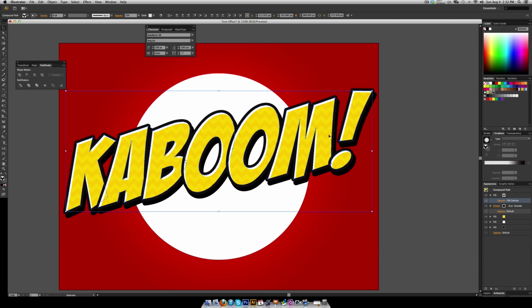The last thing we're going to do, with all the text still highlighted, is right click on any letter here, go to Transform and go to Rotate, and put in 20 degrees, but we want to uncheck Objects. We only want to do the pattern. As you'll see, it's about to change this pattern, so hit OK, and now we've got a little slanted look to it.